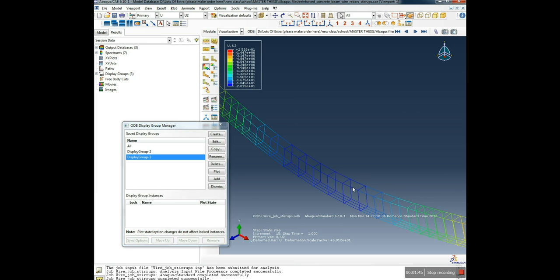So the thing is that because this beam doesn't have shear forces that act on it basically, or not much, because it's subjected to bending. What it does primarily, it's subjected to bending. Exactly. Then the biggest stresses are, let's see some von Mises stresses here.